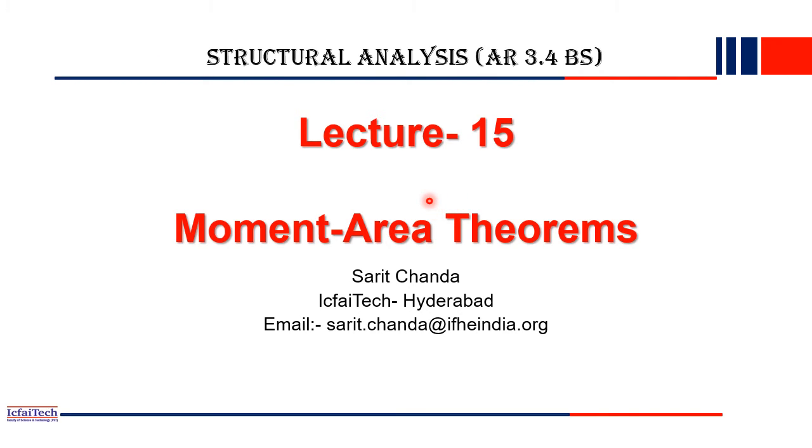So if you recall, last week we started the new module, that is deflection and slope calculation of a beam. Till now we have seen the derivation of beam equations starting from scratch, and in the last class we discussed the first method to calculate the deflection of a beam, the double integration method. So what is the double integration method? If you integrate the beam equation we derived two times, you will get slope and deflection. After the first integration you will get the slope, and if you integrate the slope equation again, you will get the deflection equation. So this method we discussed in the last class.